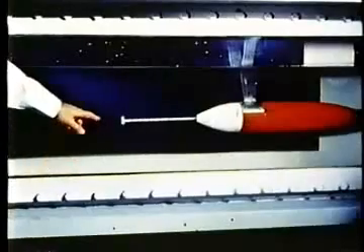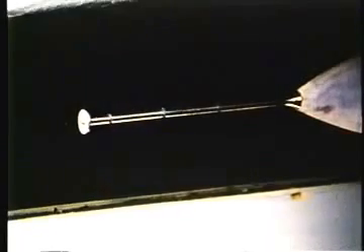For example, let's look at the flow behind this circular disc. As the flow speed is increased, the pressure fluctuations in the zone of high turbulent shear lead to cavitation. With further increase in speed, the entire wake appears to be filled with vapor bubbles. Eventually, the flow becomes a true cavity flow, as distinguished from a cavitating turbulent wake. With high-speed photography, we can see more of the details of this complex flow.